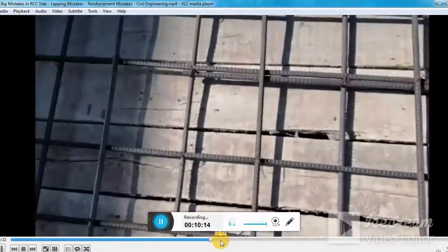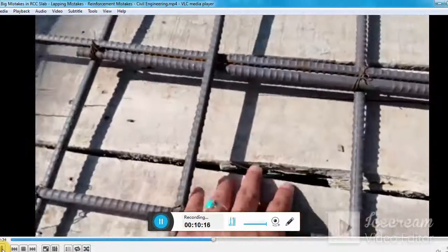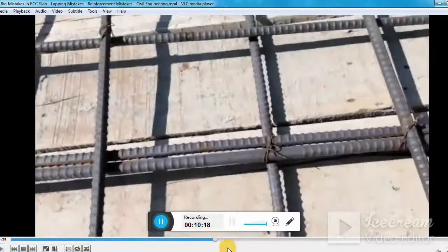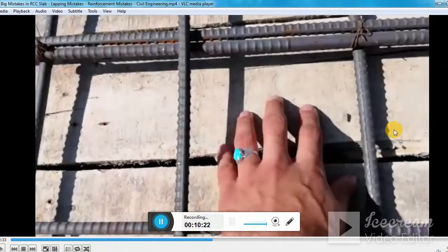I have to discuss more. You can see this is formwork, wood formwork, right? We don't allow such kind of cracks in formwork, or you can say hollow areas in formwork, because it causes bleeding and a very bad surface finish on the lower portion of the concrete.